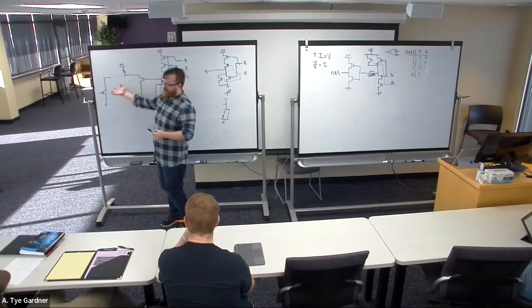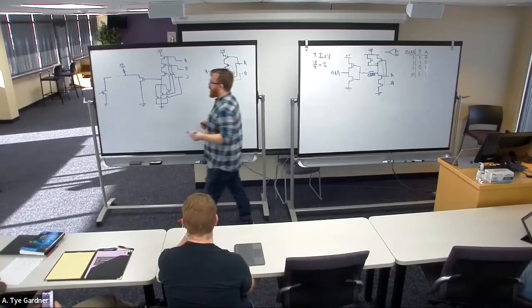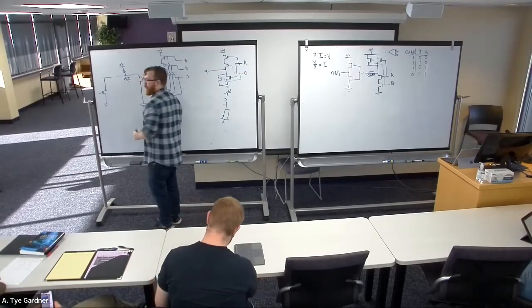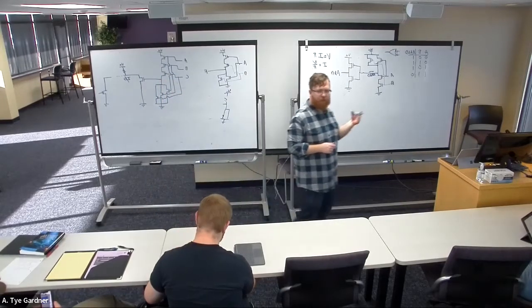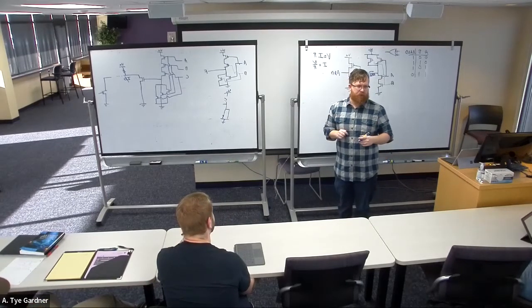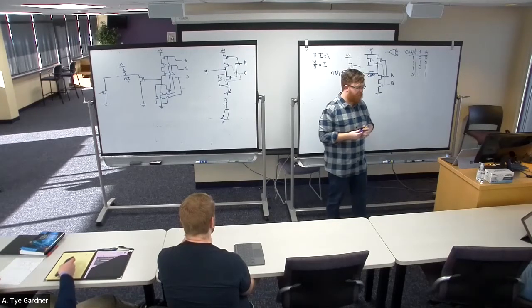We have this cool architecture called open drain architecture that allows two devices to have what is called an I/O. Sometimes you'll see a dash between it. An in-out port. We've talked about ports before in block diagrams. The port on this device is both an input and an output, which is really nice because now I can use only 2 wires, one being ground, one being the signal, in order for 2 devices to talk back to each other, and there's no chance of them breaking.